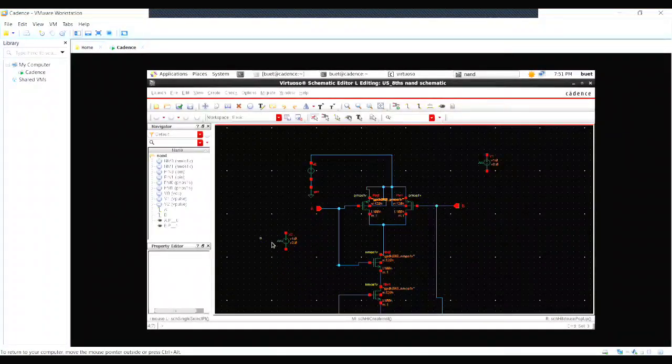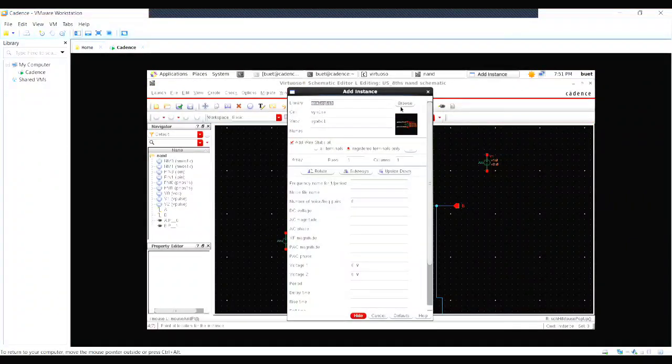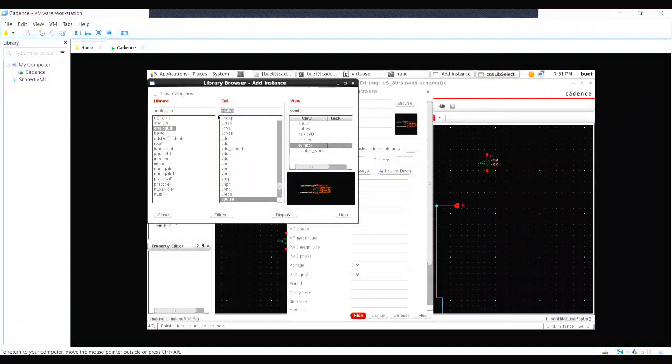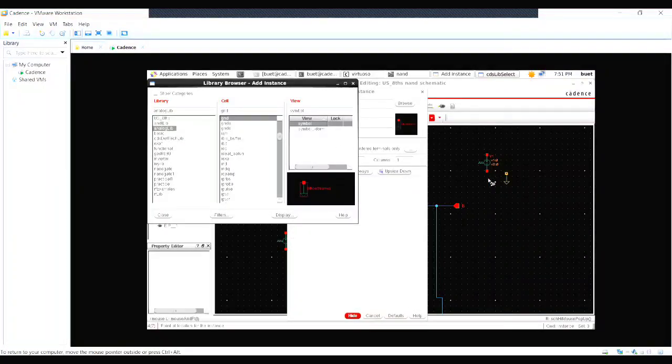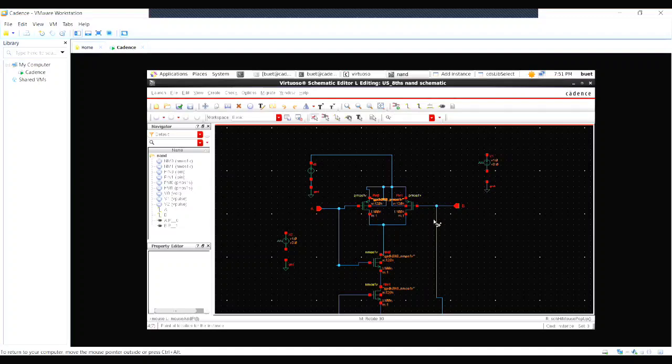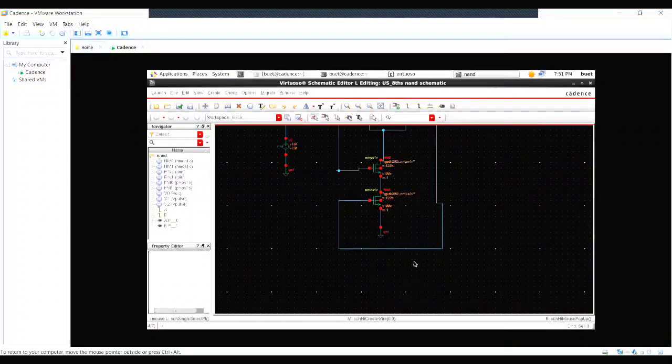Now all you have to do, for the inputs, you have to take two grounds, same as I'm going to select the ground G and D. Here for one another, here for this one. Okay, I'm going to press the W for the wire. I've successfully connected the wire, and this upper side goes to the A input, and this upper side goes to the B input.